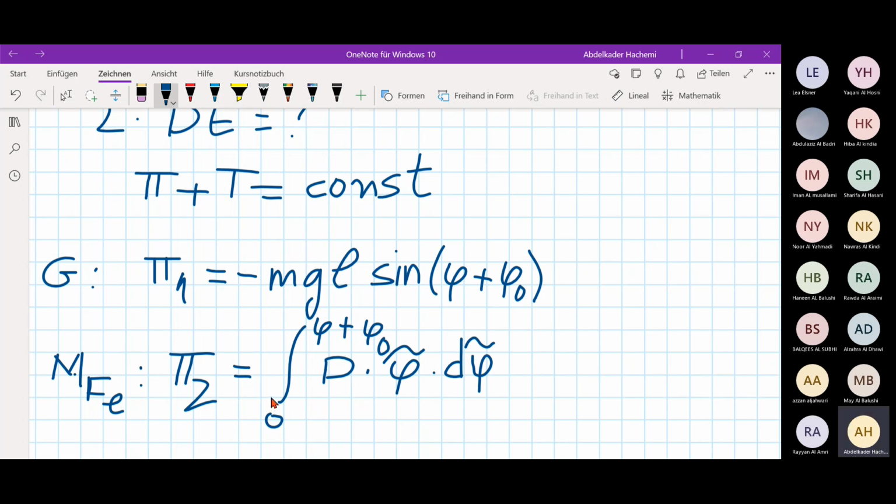In general, it's equivalent to saying you make the integral from 0 to delta s of c multiplied by s, integrating ds. And you remember we said that the potential of the normal spring is the half of c multiplied by delta s square. It's the same principle.